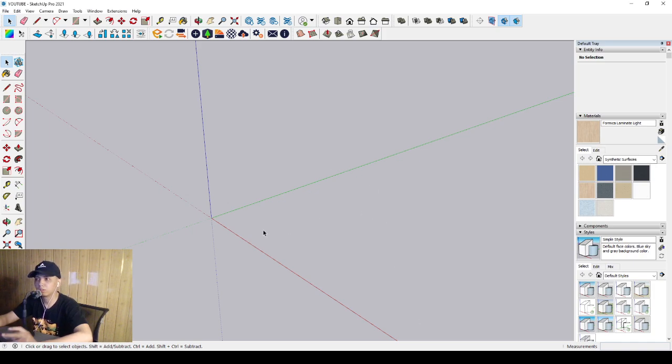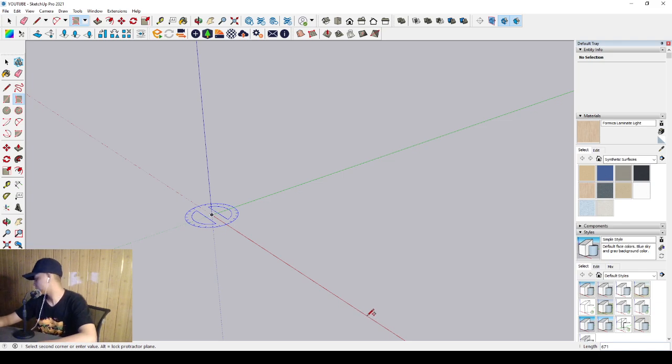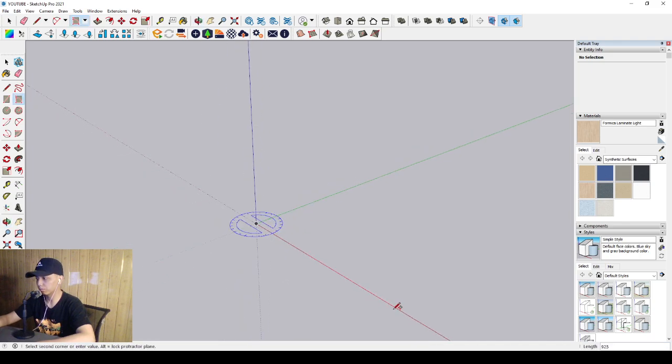In this video, I'm going to explain how to make a sliding side table. First of all, we have to make the rectangle. We can use this, or maybe we can use the rotated rectangle over there. Then we can set the length of this table to around 800 millimeter. Approximately, it's around 800 or 900. Maybe we can set it to 900 millimeter, and the width is around 500 millimeter. Okay, just something like this.